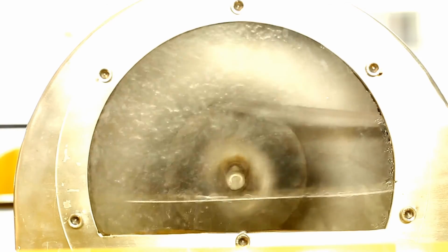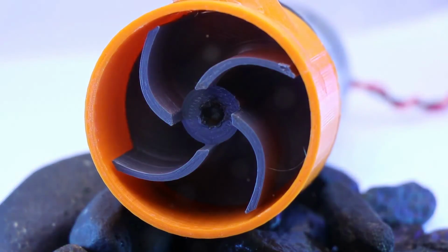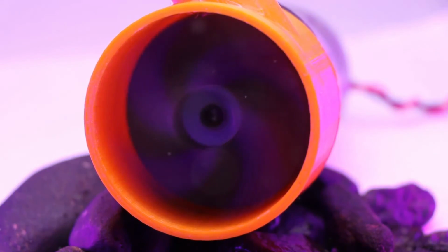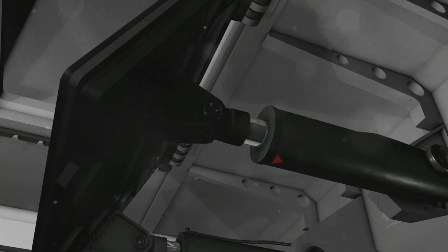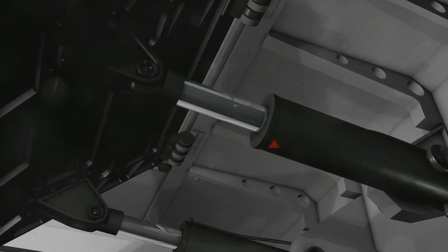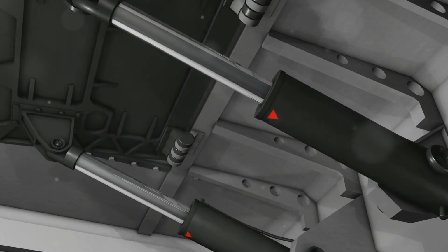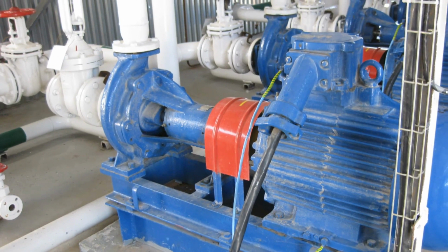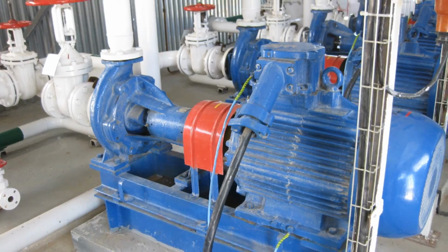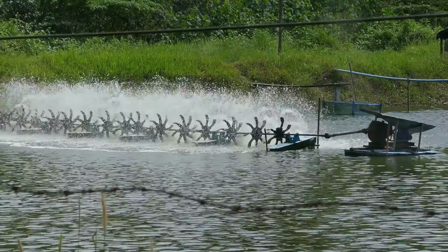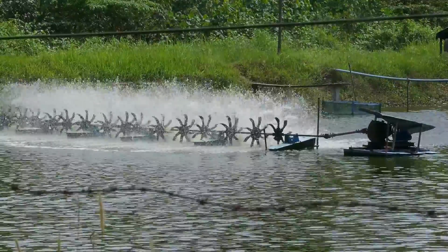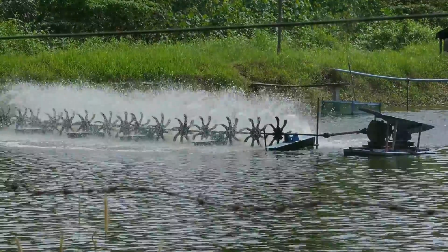Before we delve into the intricacies of pumps, let's take a moment to appreciate the role of inducers. These unsung heroes of fluid mechanics play a crucial role in preventing cavitation in pumps. Inducers are essentially axial pumps, placed before the main pump to increase the pressure of the incoming fluid. This preemptive strike against cavitation ensures smooth and efficient pump operation.